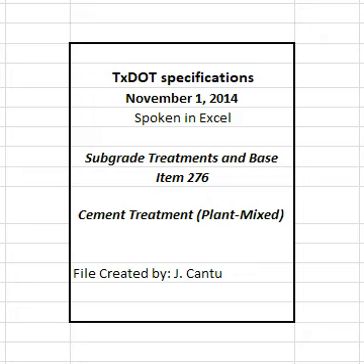4.4 Finishing. Clip, skin, or tight blade the surface of the cement-treated material with a maintainer or subgrade trimmer to a depth of approximately 1/4 inch immediately after completing compaction. Remove loosened material and dispose of it at an approved location. Roll the clipped surface immediately with a pneumatic tire roller until a smooth surface is attained. Add small increments of water as needed during rolling.